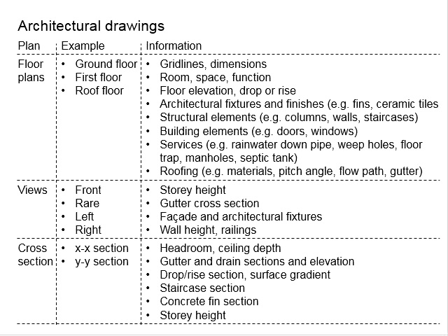You see, most of the students, when they need to design a building, producing a structural plan, refer more extensively to the floor plans given in the architectural drawing. Most of the time they overlook the details of the views of the buildings, where some information can only be acquired from the views of the buildings. This includes the story height, as well as the height of certain building elements, such as the wall, the railings, and etc. The views of the buildings also give you an idea of how the building would look. And when you design your structural plan, you need to ensure that the intended view of the building is not being compromised.